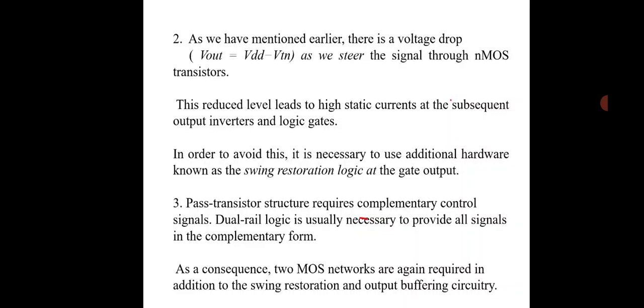So these are the different types of pass transistor families and pass transistor logic. Pass transistor logic families can be designed with the help of NMOS circuits. Coming to the advantages, pass transistor logic families can also be used to implement multiplexers like 2 by 1 as well as 4 by 1. They also have a number of advantages like being ratioless, low power requirement, low power dissipation, as well as low area. These are the advantages, right?